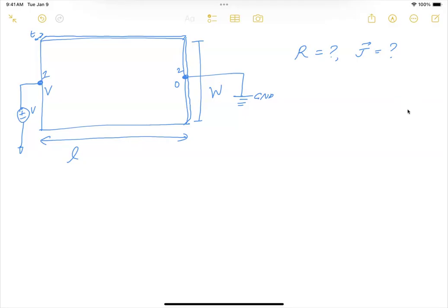fundamental electromagnetic perspective. So what is the equation that basically governs the flow of current through this material, through this voltage plane of constant conductivity sigma? It is basically the charge conservation equation, which is del dot J plus the time rate of change of the charge density with time is 0.